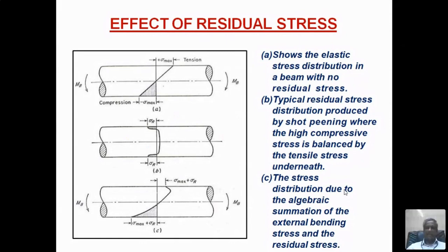And temperature, again, temperature is also very important. If the testing temperature is less than room temperature, it is low temperature fatigue. If the test temperature is greater than room temperature, then it is high temperature fatigue. And if temperature is low, fatigue strength is high. Okay, at high temperature, what happens? The fatigue failure will change into creep failure because fatigue also runs for many hours, and creep also runs for many hours. So a transition is possible at the high temperature.